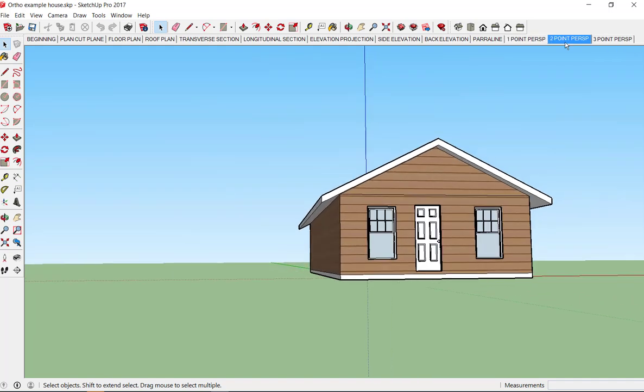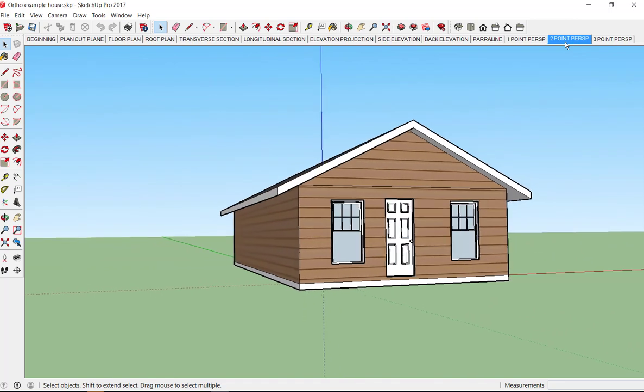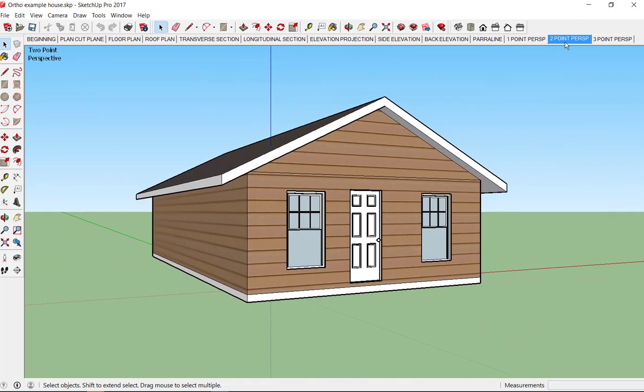A 2 point perspective is when you turn so that the front plane of the building or the object is not square onto you. Now you have two vanishing points. I'm looking totally horizontally at the building, so my vertical lines are vertical. But you'll notice that all these lines vanish out to a point to the left, and all the lines going the other way vanish out to a point, it would be off my computer screen to the right. And those vanishing points shift depending on what angle you're working at. So you can practice looking at this. A good way to look at this is to trace actual photographs and figure out where the vanishing points are.